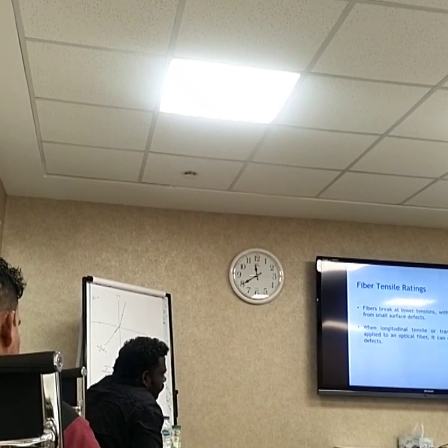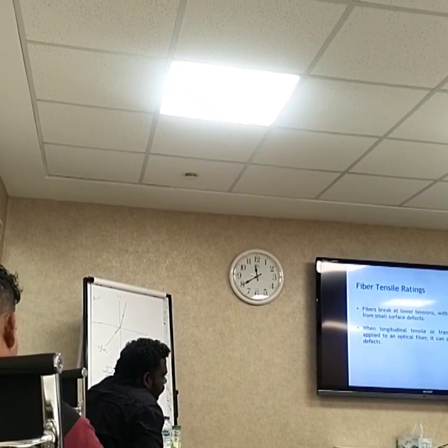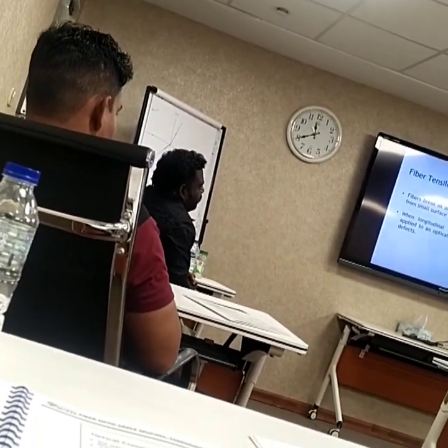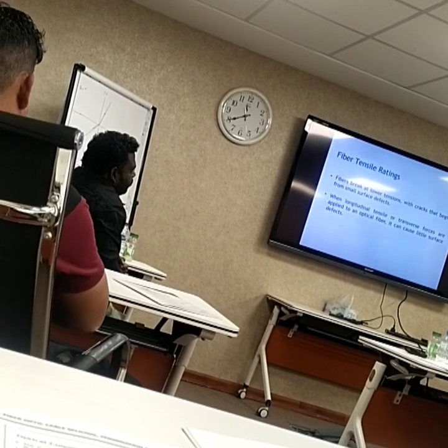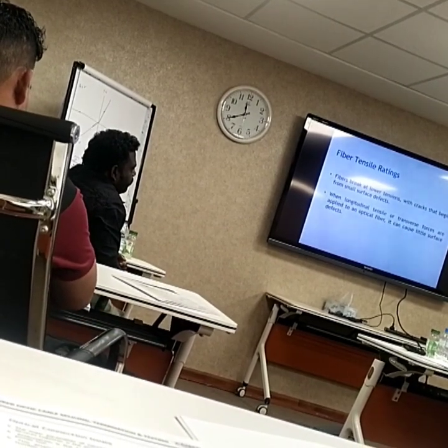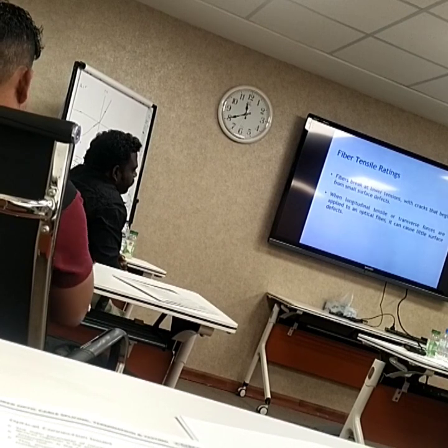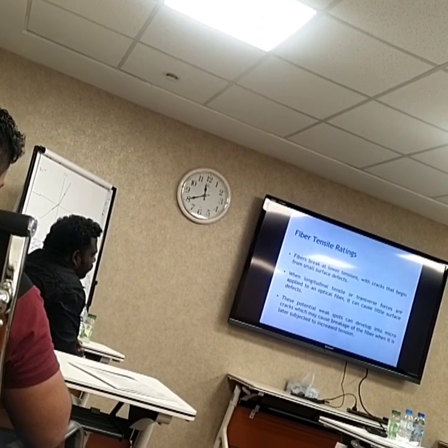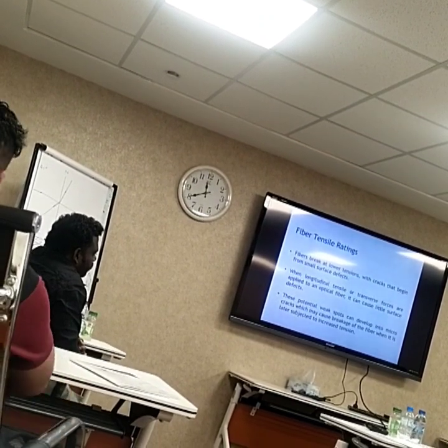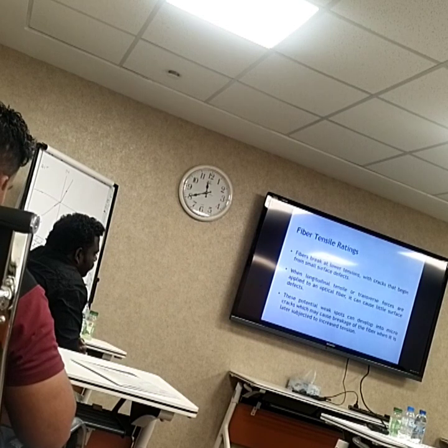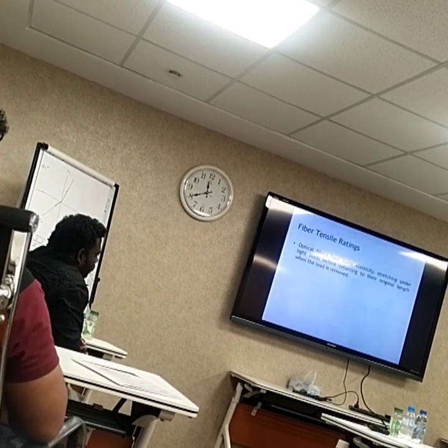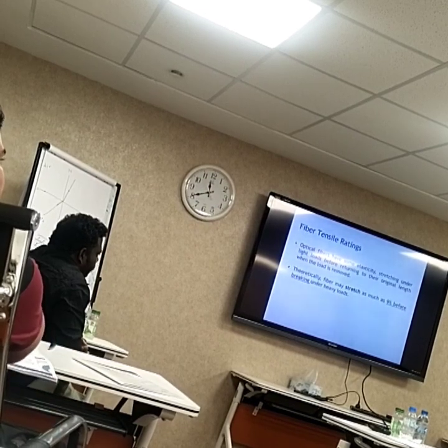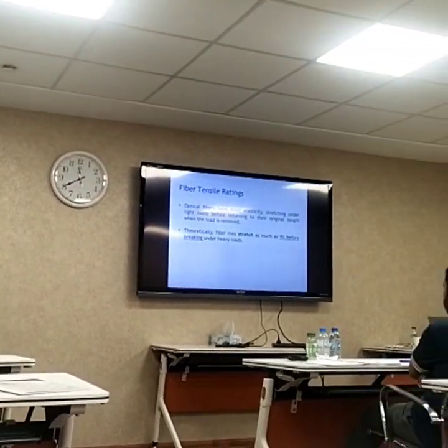When longitudinal tensile or transverse force is applied to optical fiber, it can cause little surface flaws. Longitudinal, when you apply tension force. Transverse means it's perpendicular to the fiber, when it is compressed. This potential weak spot can develop into micro cracks, which may cause breakage of the fiber when it is later subjected to increased tension.